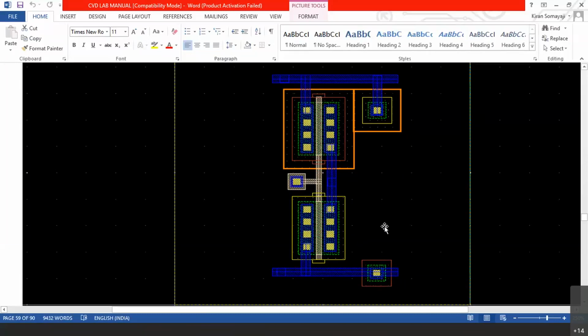So whether you put it here, or bring it somewhere here and connect one more metal layer, that doesn't matter. Now it is very near to the n MOSFET itself, that is enough. Otherwise, if you want to be specific, just like you have a wire here, you can bring this wire to the top somewhere here and connect one more metal line here for your own satisfaction. Otherwise, this area is also very near to the n MOSFET, which means the body of the n MOSFET is